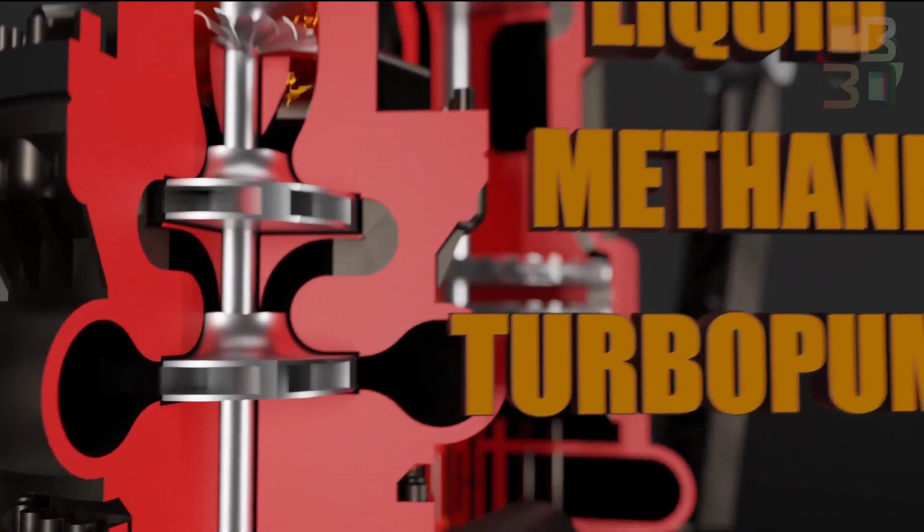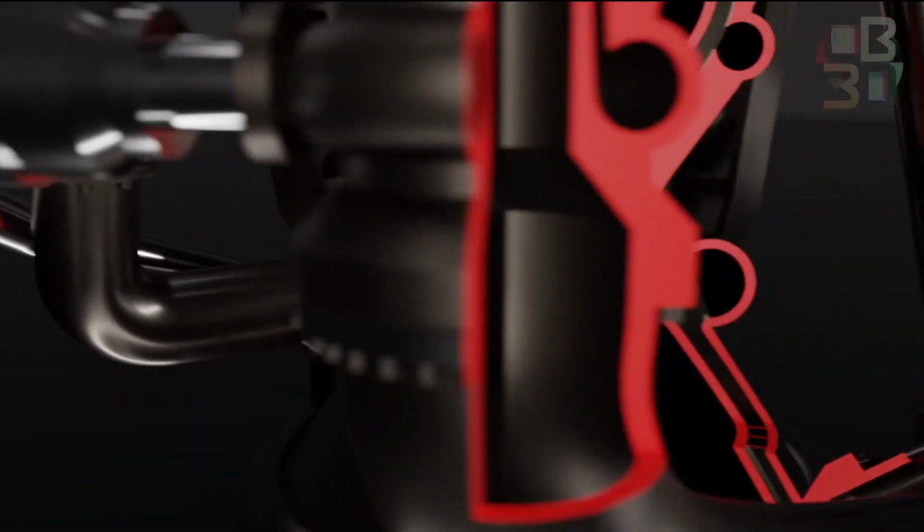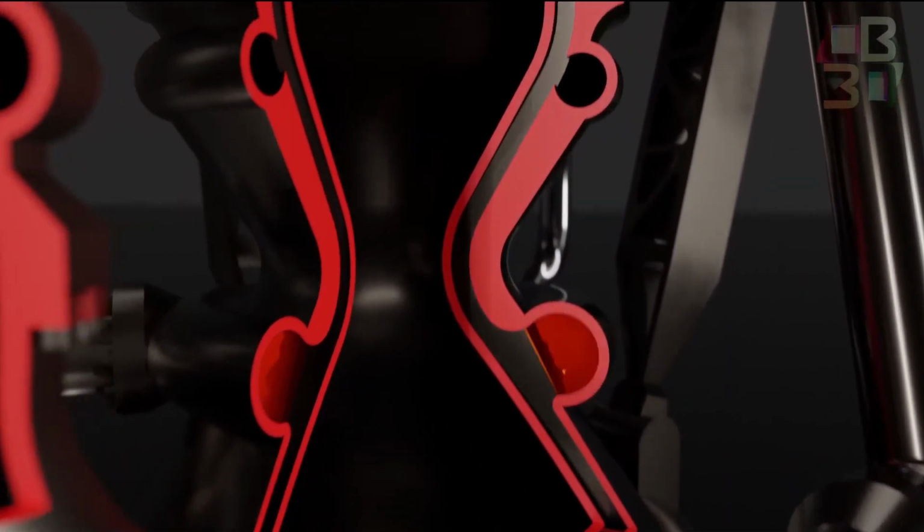After passing the turbopumps, the methane is led into a thick pipe that goes around the throat of the engine. Since the throat is by far the hottest part of the engine, it needs the most cooling. Therefore, the cryogenic methane gets pumped to the throat before reaching any other part of the engine, because every cooling system warms the methane to a certain degree. When the throat is reached, the methane is still as cold as it can get, but gets slightly warmed up by cooling the throat's outer perimeter.